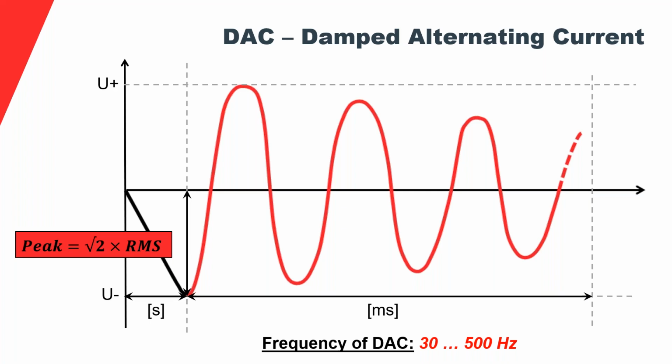And remember when I mentioned the resonance test sets? Well, in the mid-90s, when these resonance test sets came up, there was something called the IEC power frequency range. It was something they came up with in the standard to govern the resonance test sets, which would tune themselves to the cable capacitance. Sometimes the frequency is lower when the cable is longer, and then the frequency goes up when the cable is shorter. So they established this band, initially 30 to 300 hertz, then 30 to 500, and now 20 to 500.